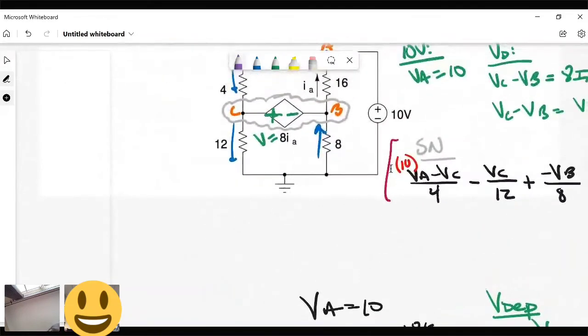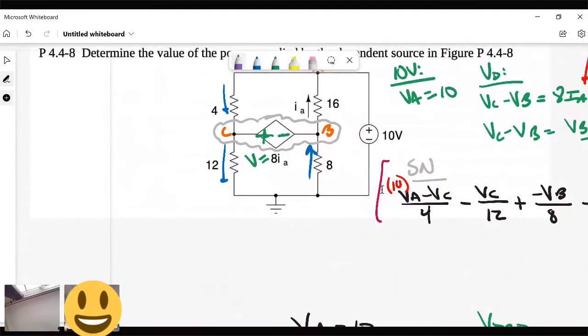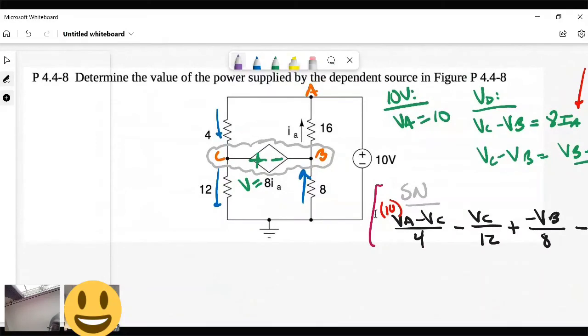So whenever you're thinking about stuff like that, take a look at your circuit. Basically, you want the current that's coming out of this guy. The current's going to go like that through it. So that's going to be the current through the dependent source. How can I find it? You don't know an equation that's going to automatically give you the answer for that current. So it's not like you can use V equals IR. Remember, V equals IR only works for resistors. And there is no equation for a dependent source that can give you the current.